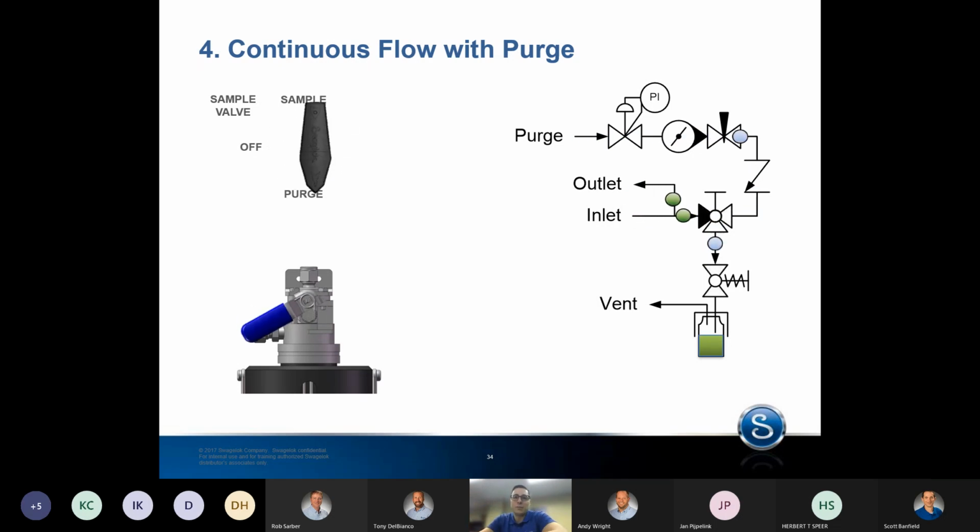And you would rotate your sample valve to the purge. What that's going to do is allow your inert purge gas to flow down through the three-way valve to your MBS sampler, which you would depress for whatever duration of time is suitable for your needs, and that would flush any process out and up through your vent needle on your MBS sampler. So now your system is completely purged clean. You have a fresh representative sample with the correct volume in your bottle, part of the panel, and you're able to remove the sample as intended.